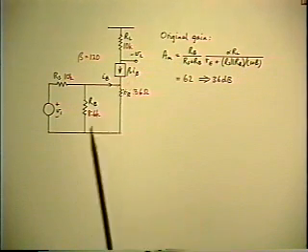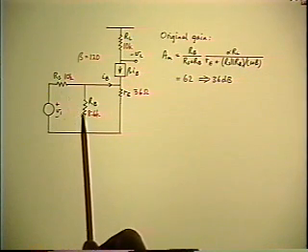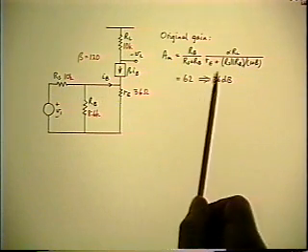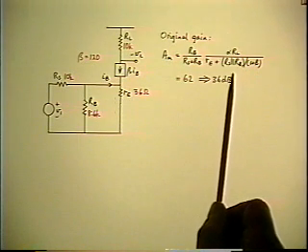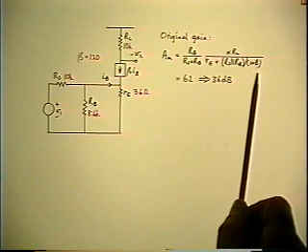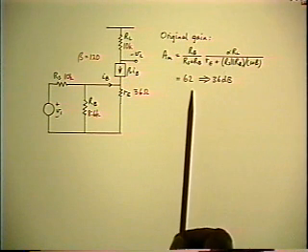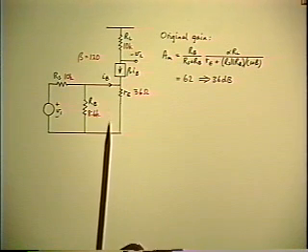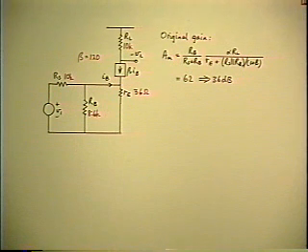And once again, you could go through the mental circuit reduction, eliminate one loop by Thevenin, which gives you the Thevenin divider in front, reflect the base resistance into the emitter. Thevenin voltage is applied right across the combination. So the denominator gives you the emitter current multiplied by alpha multiplied by RL. The result is 62 or 36 dB. That's the mid-band or infinite frequency gain when coupling and bypass capacitor are zero impedance. So suppose we've done that.